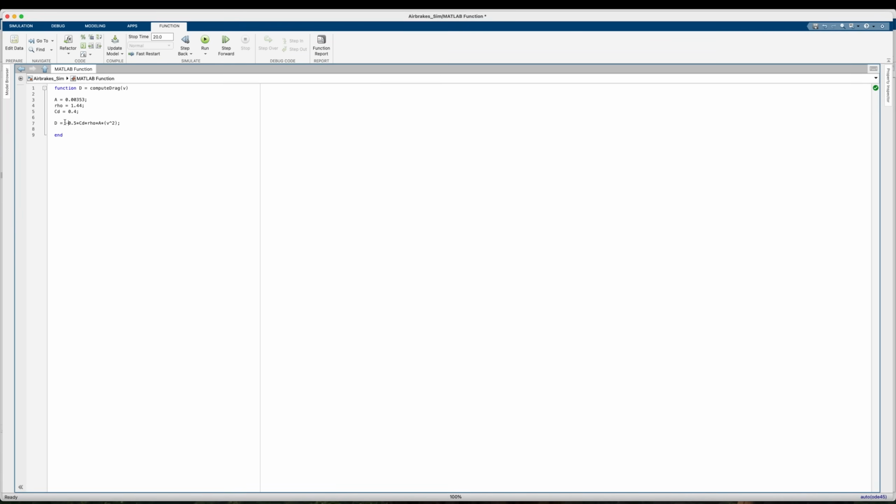So we're going to add a negative sign here to make sure that our drag force is applied in the opposite direction of our vehicle's motion. This model actually just applies it towards the ground no matter how your rocket's traveling, so this will actually accelerate our rocket towards the ground, but if we did a little bit of vector math, we could apply that. In our case, we only care about the drag force on the way up, and then we'll just stop our simulation at apogee, so this is fine for now.